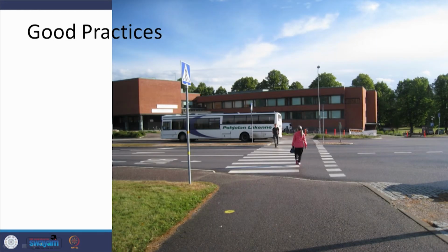Okay. So, similarly here what you can see is that there is a pedestrian crossing which is marked. So, you have a wide pedestrian crossing in this case, and this is also being provided with this line, that means there is a gap here. So, the bicyclist can use it. This is a footpath, but this footpath is raised, but when it comes here then the slope is being provided so that it comes at the same level as the carriageway.